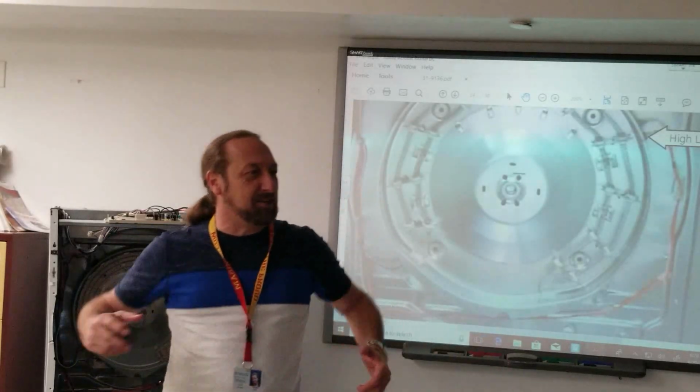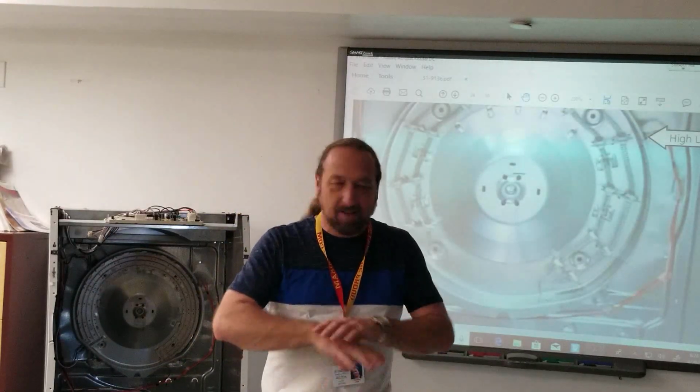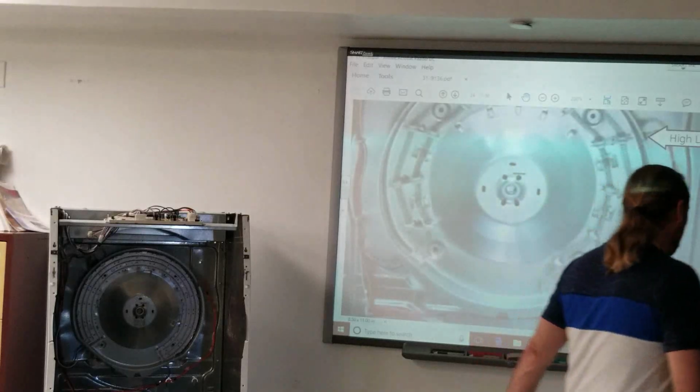I mean, these guys are so gung-ho: I'm going to hook up gauges, I'm going to check pressures. You know, you have to take a few minutes. Don't throw tools on the machine right away. Look and evaluate what it's doing, okay? So let's move on.